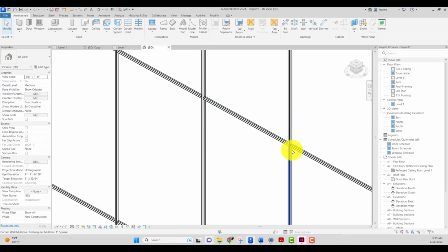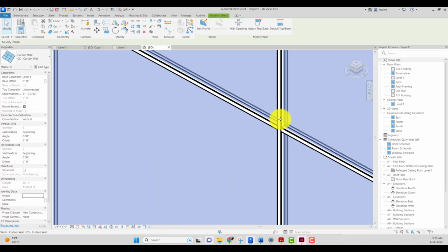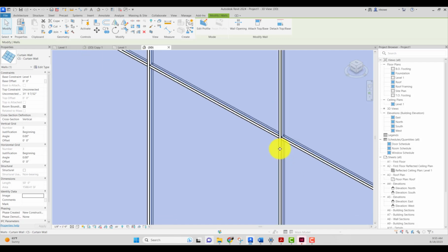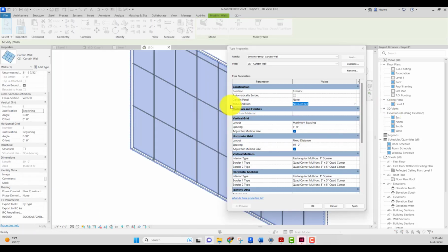Okay, so the other thing to notice is that right now it's showing vertical as continuous, and then segmenting. Even though I can select just a segment of the vertical, visually you can see that it's continuous, right? You have control over that too. So if you didn't want the vertical to be continuous, you could go to the join condition, and you see the default apparently is vertical grid continuous, but it could be horizontal grid continuous.